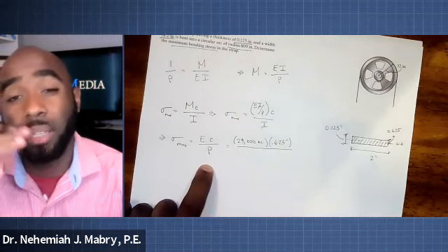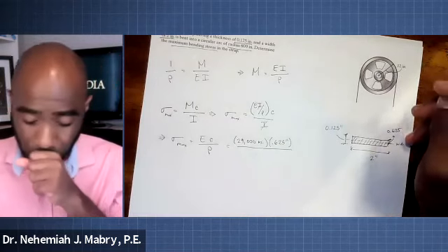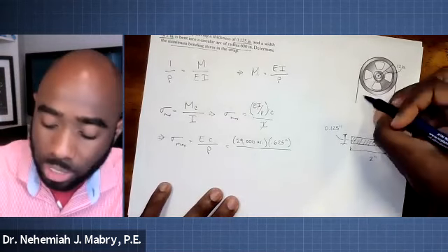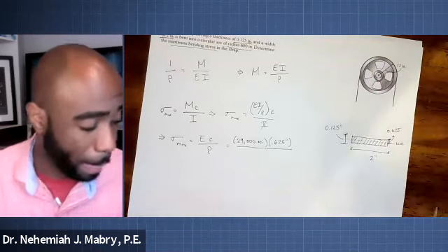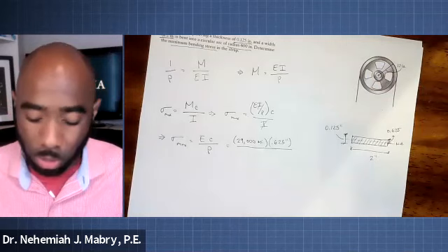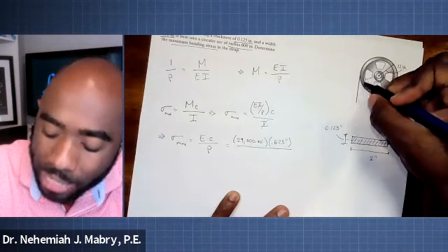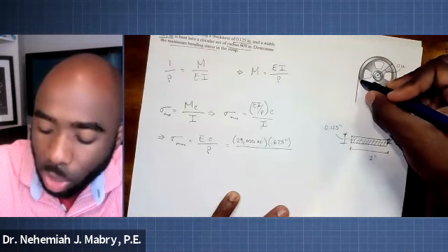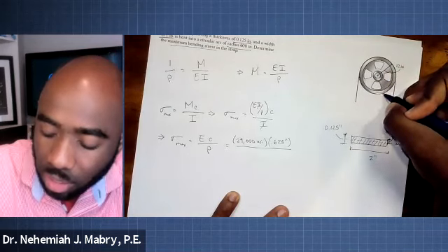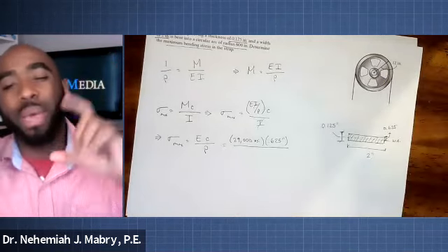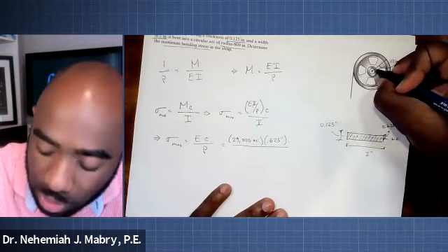Well, the definition is the radius of curvature. One of the things that's actually helpful in this particular problem is that it tells us that this strap is being bent around this entire hoop here. Since that is the case, we don't have to imagine that it's around some imaginary circle. We can simply use this right here as that circle that I just explained to you. And therefore, the radius of curvature is the distance from the center to the strap.